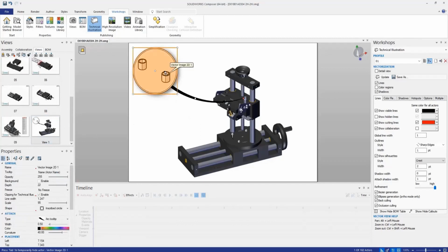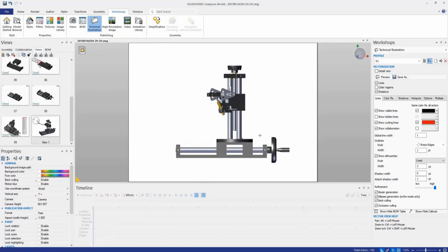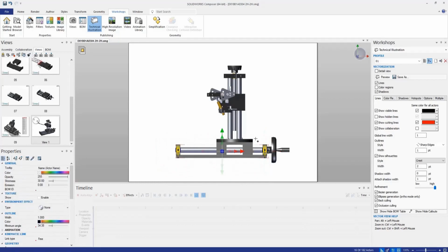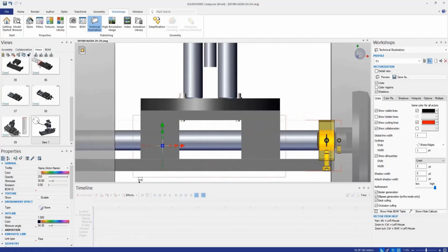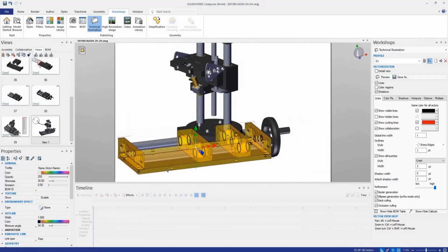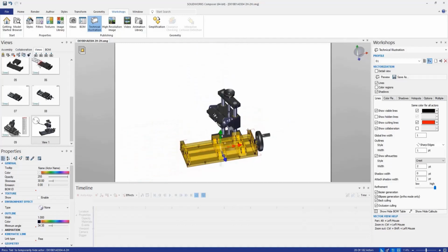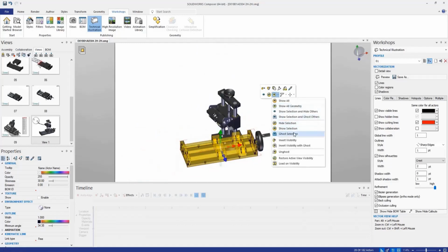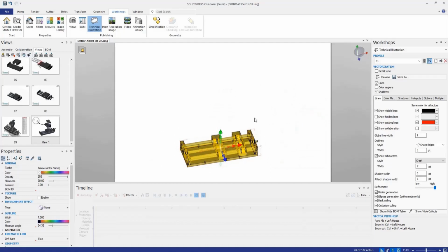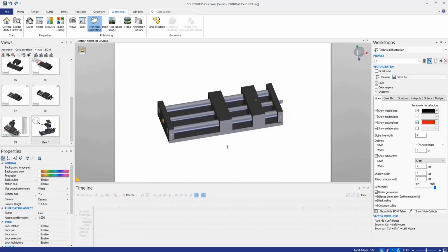As you can see, the view has been saved, and the image is already available there, so you can move forward to do some other work or create other views as well. So let me quickly select the parts on which I need to do some work. Okay, I am selecting all the parts which I require for the next view. You can either select through drag and drop windows, or you can also utilize the one by one single select functionality, and then you can select options like show selection and hide others, which can help you generate the interactive view at a faster rate.